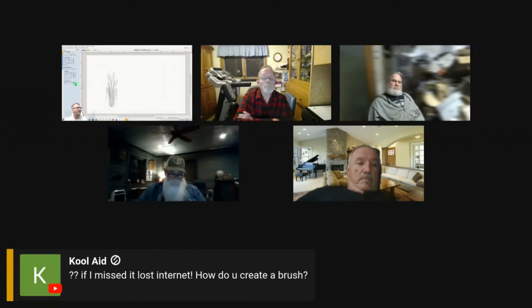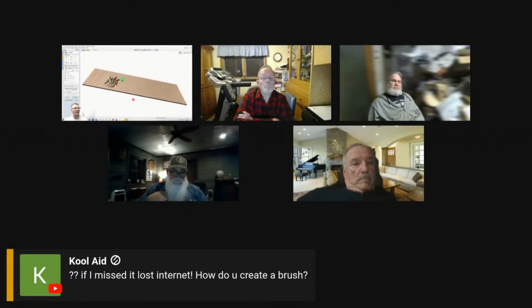All right, so I got to give it a background. So we're going to go to the modeling tools, create shape. I'll just give it an 1/8 inch flat background, 0.125. Click apply. All right, so now I have a background. Now I can come in, sculpt.